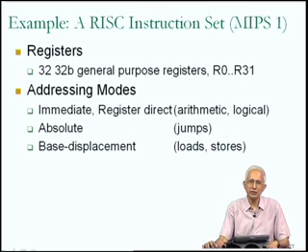Next, the base displacement addressing mode is used by load and store instructions. And you will recall that the base displacement addressing mode is the one where the operand is coming out of memory, but the address of the operand is calculated as the sum of the contents of a base register and a displacement, in other words a small signed value which is contained inside the instruction. So after adding these 2 values, one gets the address of the operand in memory, and this is used only for loads and stores.